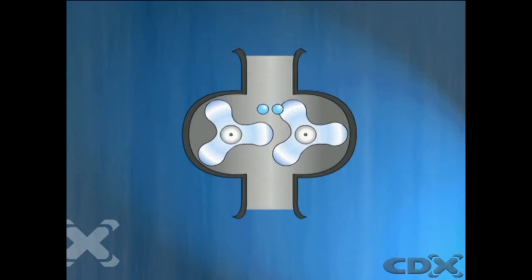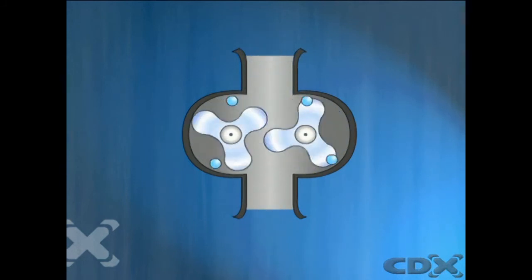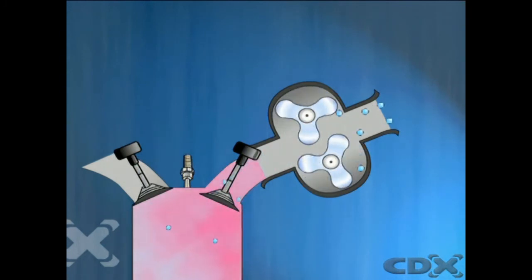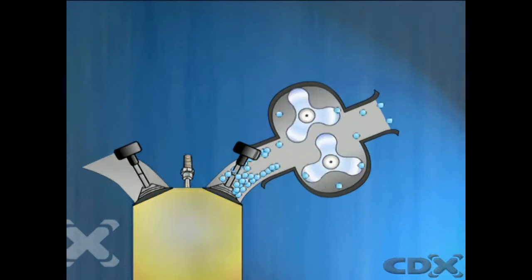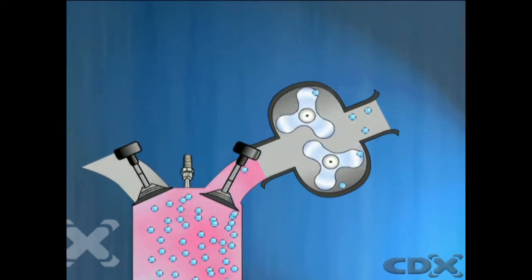In a supercharged system, there is a greater air mass flow rate, that is, a higher density and speed of airflow. Air pressure is increased by the compressor on the way into the engine, more power is produced by combustion, and the exhaust gases exit much more rapidly, making the timings and exhaust sizing less important.